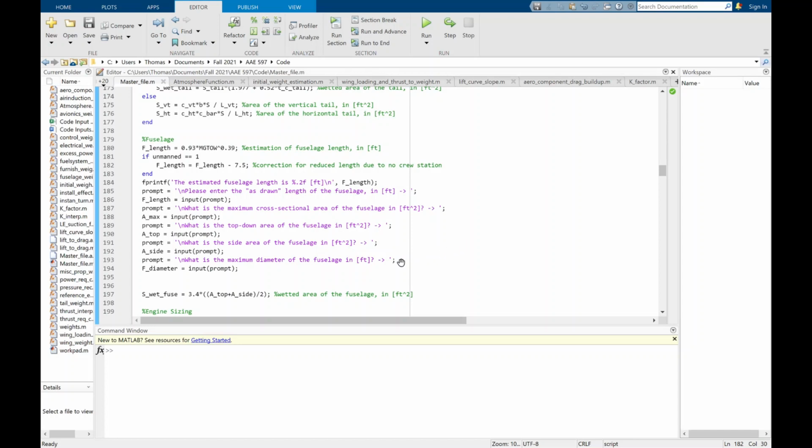And then from there we can sketch in the fuselage, generally based on the avionics volume, where the pilot would be if it was a manned aircraft. This is the unmanned layout, and then also how much fuel and payload needs to be internal to this body. So from there, we know each square is 2 feet by 2 feet. We can count from here to here. Ends up being about 43 feet for this iteration.